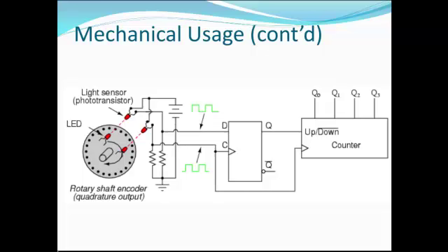If we wanted to make this mechanical system more complex so as to count up when the encoder is rotating one way, and count down when the encoder is rotating the other, we could add another LED paired with another light sensor so that the output of this new light sensor is 90 degrees out of phase with the original light sensor. We choose 90 degrees because then the circuitry may have time to set up and process the data as expected, as there are delays.